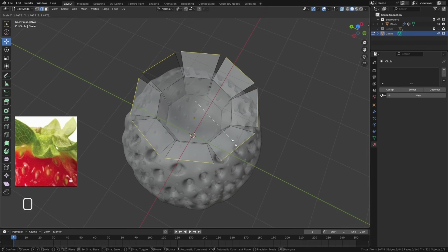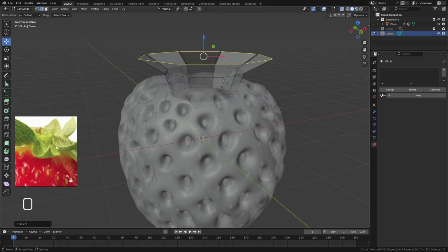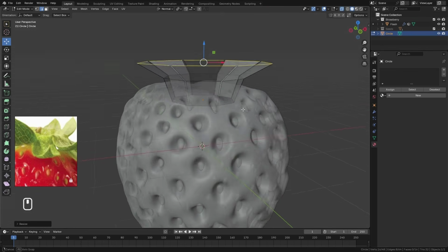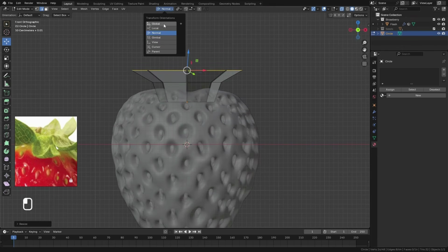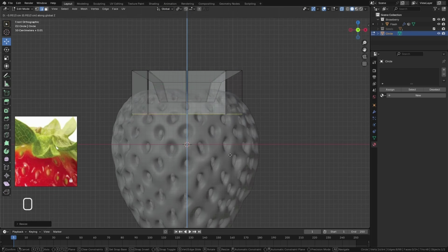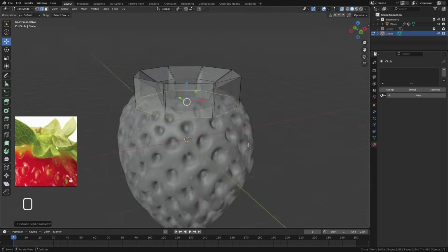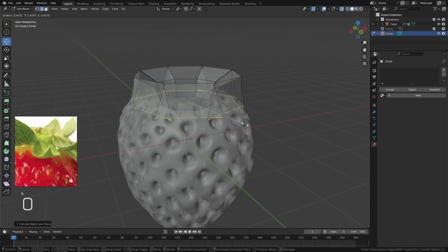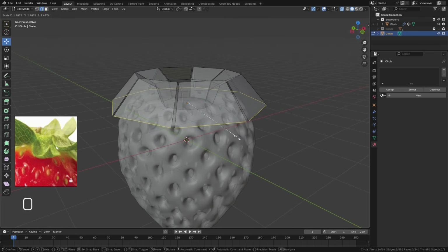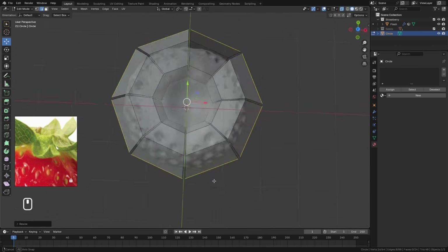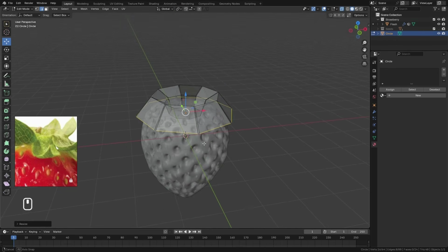Yeah. Make them close together, right there. Now we need to drop them downward, back to front view, and switch to global. And E, Z. Maybe around here. Again, S. Not individual, this time median point. So S goes right there. They're really big, right?